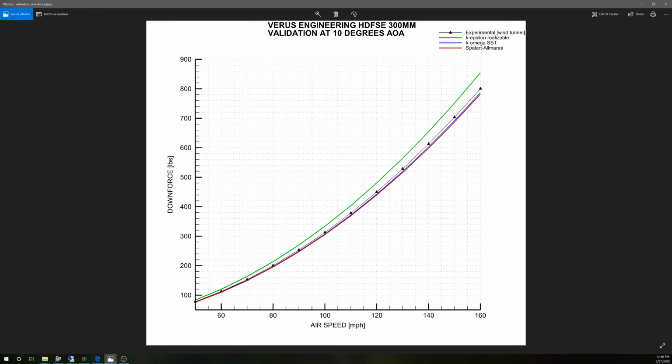So this is what the correlation looks like. This is actually what was done in Fluent, so you can see the difference when we were still using Fluent in the correlation work. We use this model a lot because we have wind tunnel data, and now we have two different CFD setups going in there. So that is where we use it a lot, so we can compare different runs. You do a lot of mesh sensitivity studies with it. We can do a lot of different things on that. So having the wind tunnel data is very, very critical.